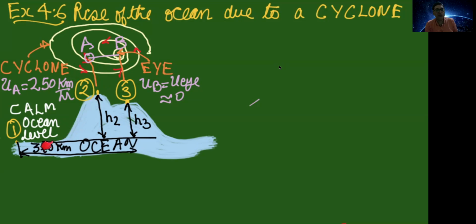From fluid statics, you know that if at a certain location the pressure is atmospheric, and at another location you have sub-atmospheric pressure, then if you draw a horizontal line from here, everywhere the pressure should be atmospheric. So if the pressure is subatmospheric at some location, then the level of water has to rise for the balance in the pressure.